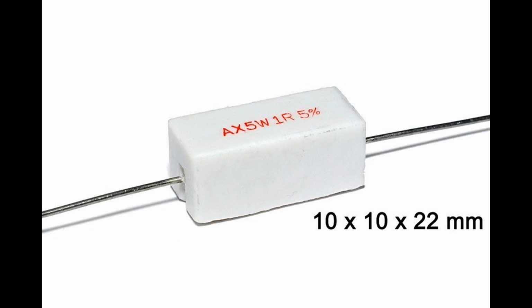The specific application of fusible resistors depends on the requirements of the system or device they are integrated into. Their role is to act as a safety mechanism that disconnects the circuit when overcurrent conditions are detected, thus protecting sensitive components, preventing damage, and ensuring the safety of both equipment and users.